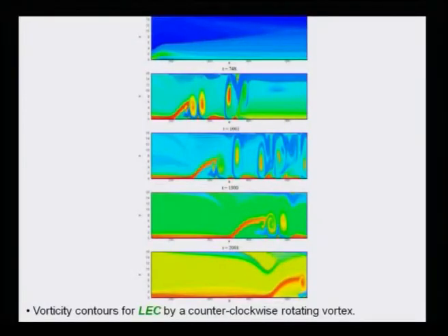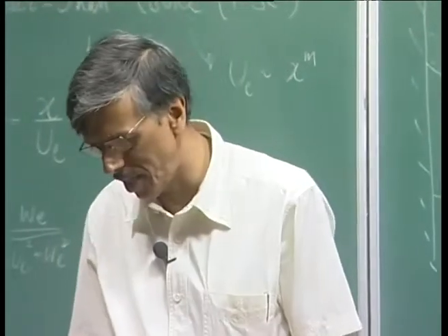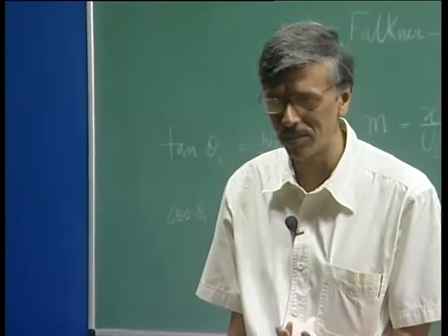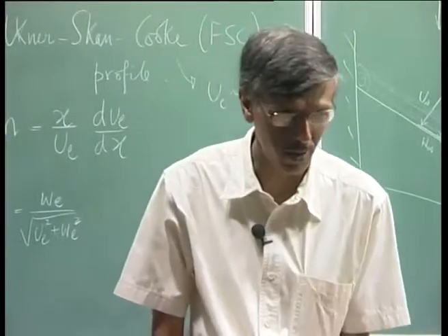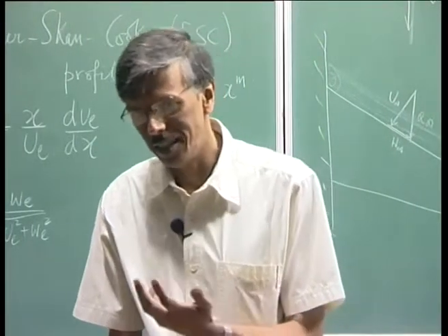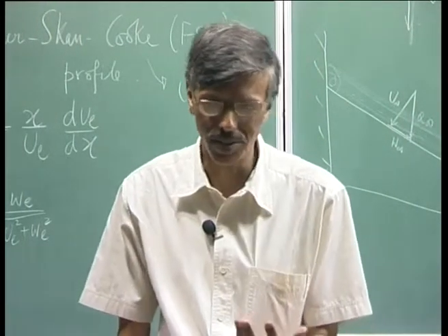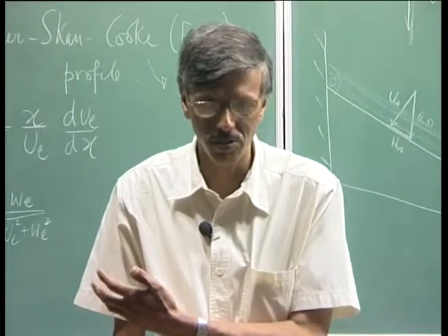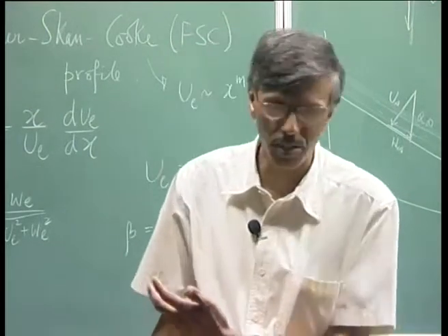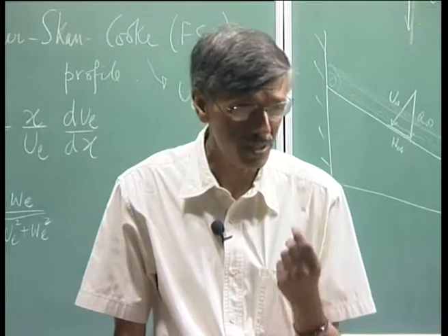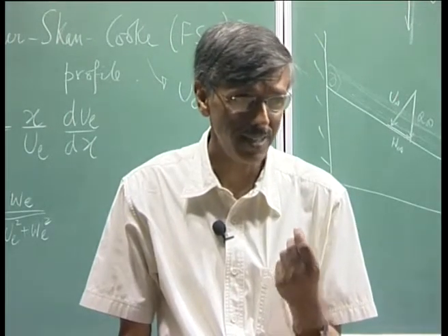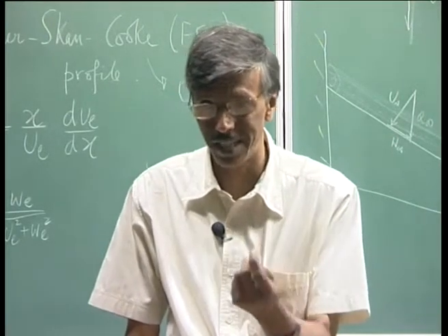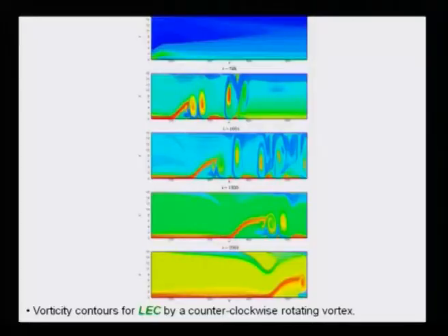So, please do not try to view it like the usual eigenvalue analysis always looked at, where you have a time independent equilibrium flow, and the instability is one of how the disturbance grows in space. However, in this solution of the Navier-Stokes equation and the attendant description that we are talking about, we really do understand that there is a time element playing a big role. That is what we are doing, right? We are calculating the pressure gradient as a function of time at a fixed location, and we do see that.